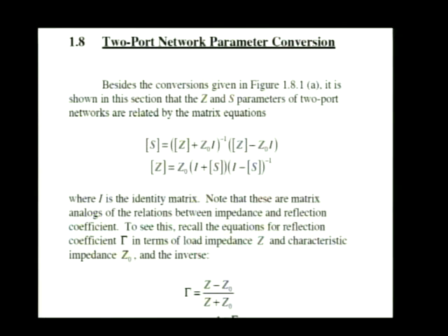It's also interesting to make the comparison of these matrix equations relating the scattering matrix and the impedance matrix to the analogous equations which relate reflection coefficient gamma with a load impedance Z on a transmission line of characteristic impedance Z0.